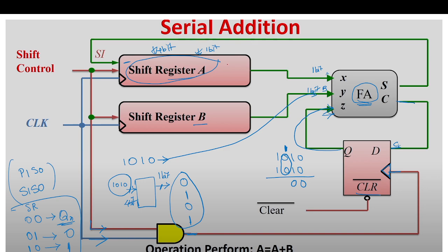Yeah, in half adder there is no carry. The difference between full adder and half adder is, in half adder the inputs are A and B, and for full adder we have the inputs A, B and C in, the carry. So if we don't want this carry propagation, if these results are fine, then we can go with the half adder. Half adder will give one result here. Carry out is there in half adder, but not the carry in.